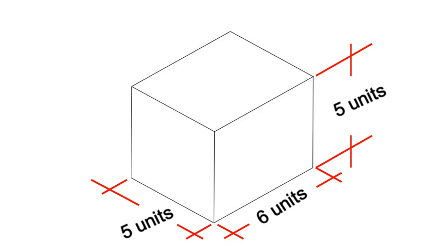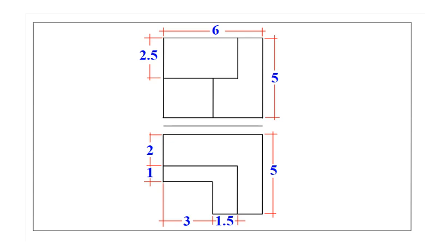Alright, now that we know we have all the dimensions, let's start building this 3D model in our minds, and we're going to start from the top view. Looking down at the top view, I can see we have two distinct L-shaped features. Now, the top view by itself only gives us a flat 2D blueprint, it gives us the X and Y coordinates, the plan. To make these shapes three-dimensional, we absolutely must refer back to our front view to get that crucial third dimension, the Z-axis, which is the height.